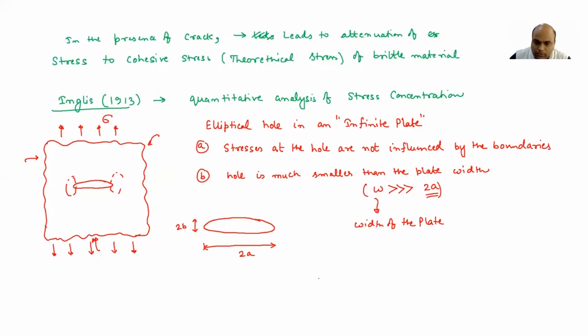Okay. So the formula he proposed for stress at the crack tip: if I denote this as sigma tip, it will be sigma tip equal to sigma (1 + 2a/b).